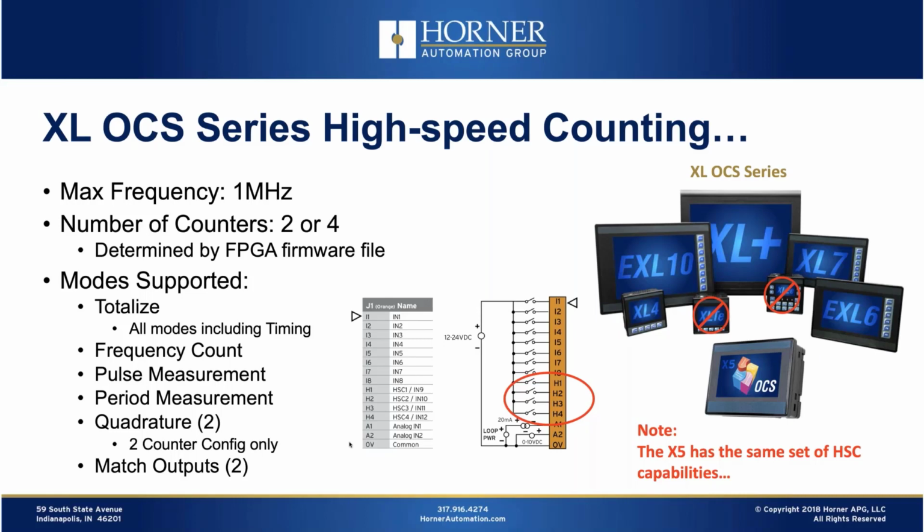Now, one thing that's a little bit of a compromise here is because the XL series FPGA chip was designed several years ago, it supports either 2 highly functional counters, or if you change a file in the firmware and update the firmware, and you can get that file from our tech support group, if you do that update to the FPGA file via firmware, then you can get up to 4 counters. They're just not quite as capable. They don't have quite as many options. So if you want to support 4 counters, you will have to load a special version of firmware to do that. But it's not a big deal.